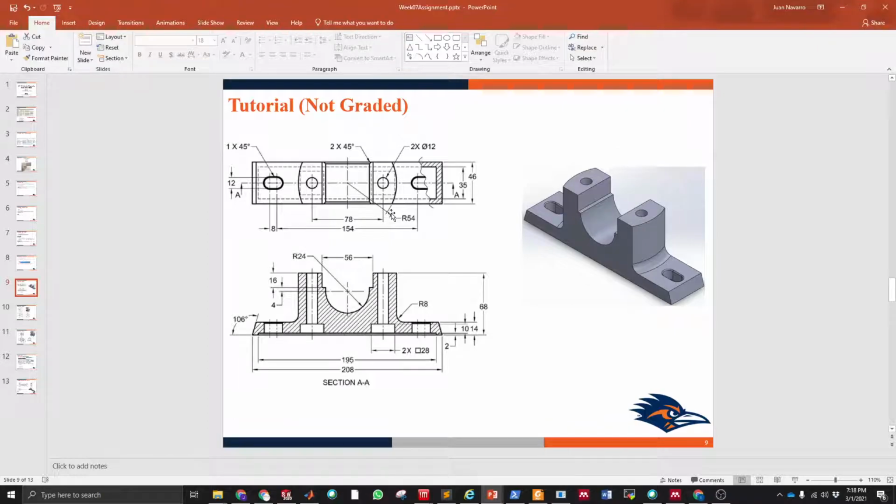And then I can take advantage of the symmetry plane of this figure. As you see, it is symmetric. I can divide this figure right and left, and it will be just the same. So I'm going to just model one half, and then I'm going to use the mirror entities to complete the other half.